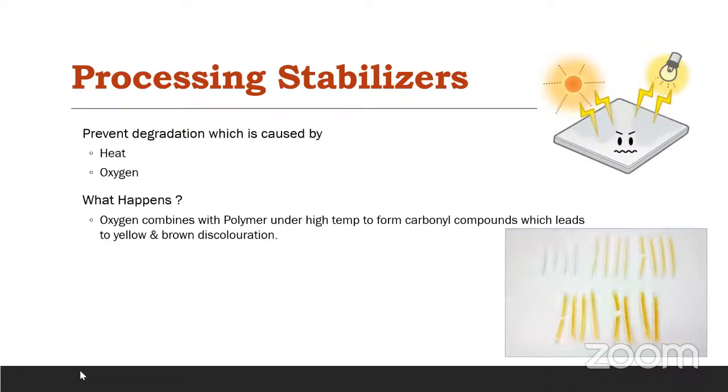Okay, now talking about flame retardants, what is the chemical added for that? Previously, antimony based products were added. There are organic and inorganic flame retardants. When you talk about inorganic flame retardants, generally phosphorus based flame retardants are being added, or ammonium polyphosphates, we can say. That is one example, ammonium polyphosphate.